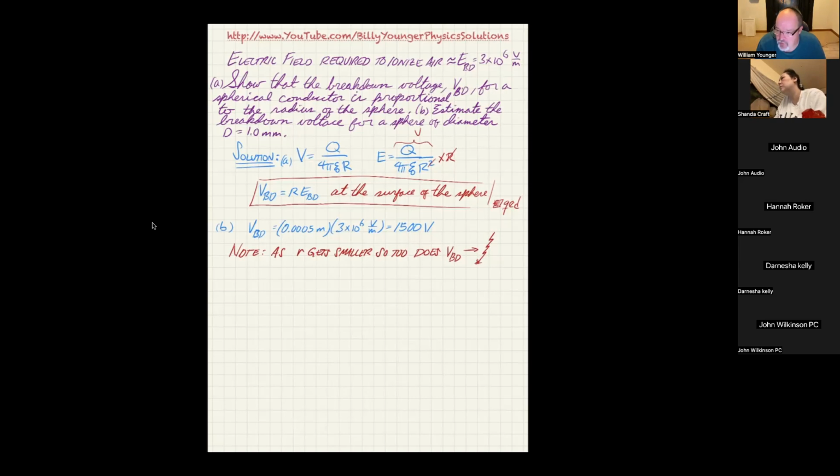Those lightning rods can be thought of as little cylinders with a little sphere on the end, and it turns out that the smaller the radius of that sphere is, the smaller the voltage difference between it and some cloud, for instance, has to be in order for lightning to discharge from the cloud to the actual lightning rod. And in fact, you'll even get what we call a corona discharge, a glow around the tips of the individual lightning rods.